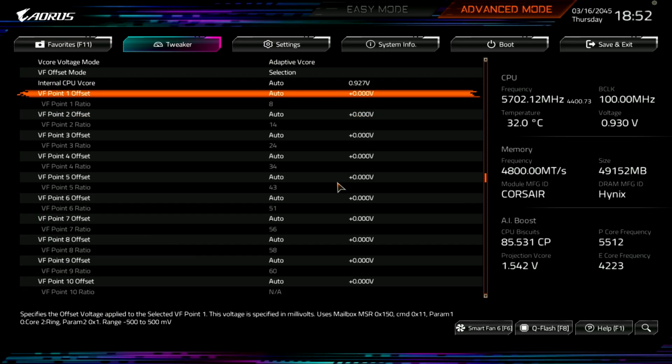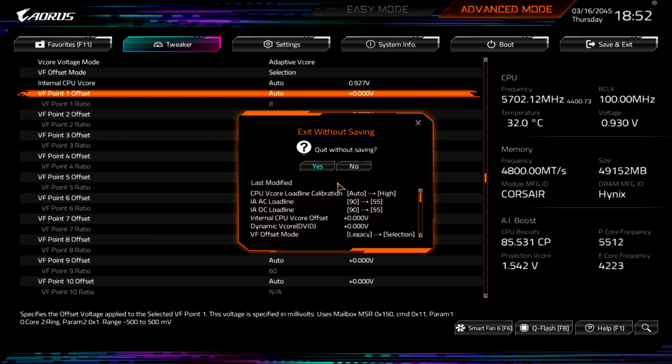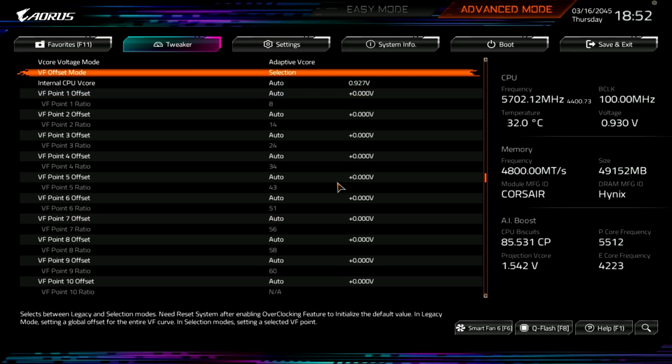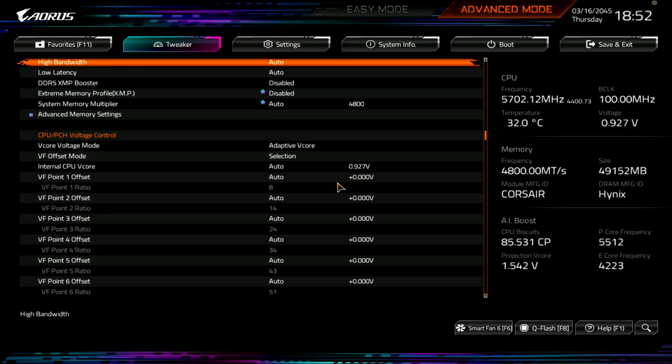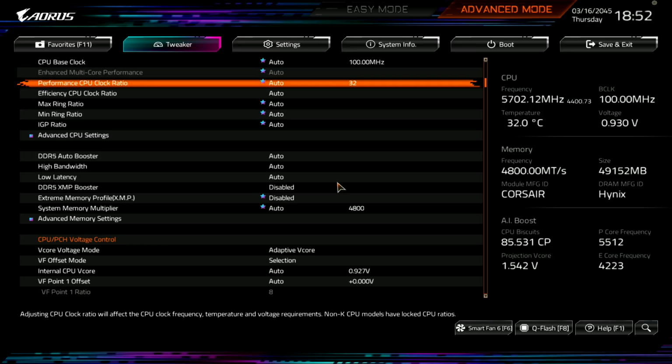We'll see. I'll look at what's available on MSI boards, and if the VR voltage limit isn't available, well, I guess don't run i9s on MSI boards, because you'll have no way to lock the max voltage below what Intel locks it to. I'd like to believe that Intel's internal reliability test data is good enough that the new 1.55 volt limit is correct and it's a low enough limit.